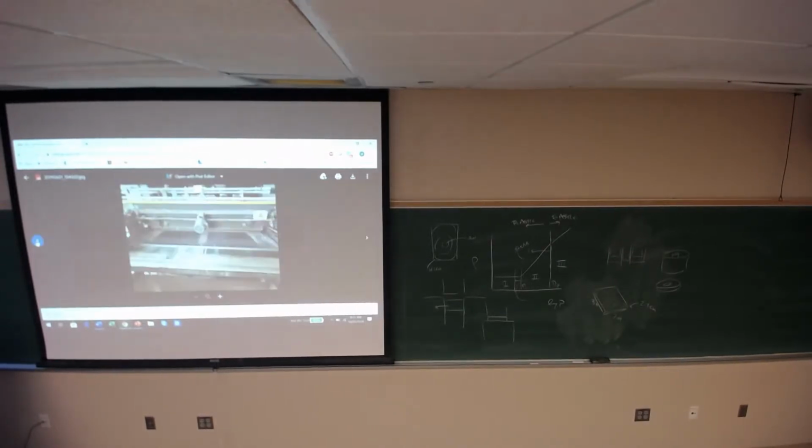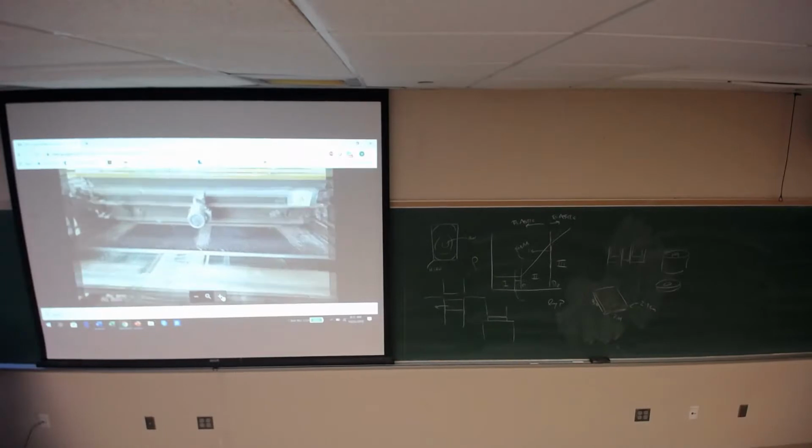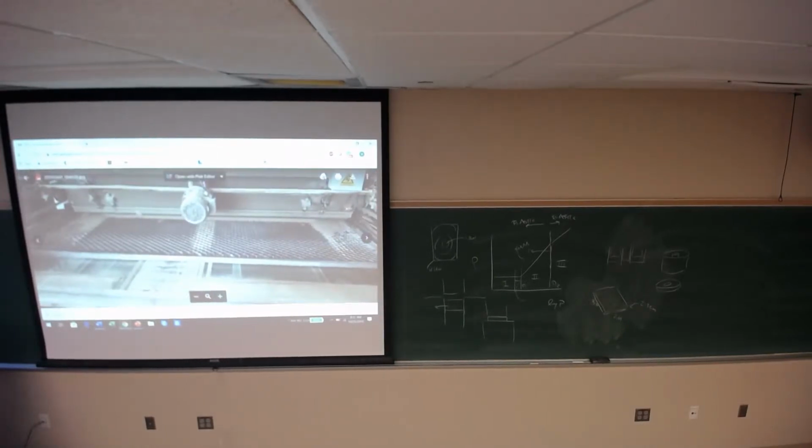You may think I have a romanticized view of China, but the fact is that that's the way they see the problem. So this is die fill. And the trick for die fill is that you see the next image. They have small volumes. You cannot fill powder uniformly within a large area. Do you know why?